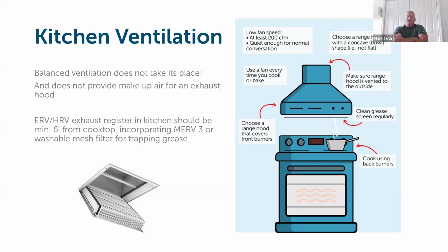Yeah, you definitely. So if you have a kitchen range hood, I mean, you're talking in this thing here, 200 CFM. Well, I'm regularly seeing in new construction 6, 8,000 CFM. That's a lot of air. You have to have makeup air for that.